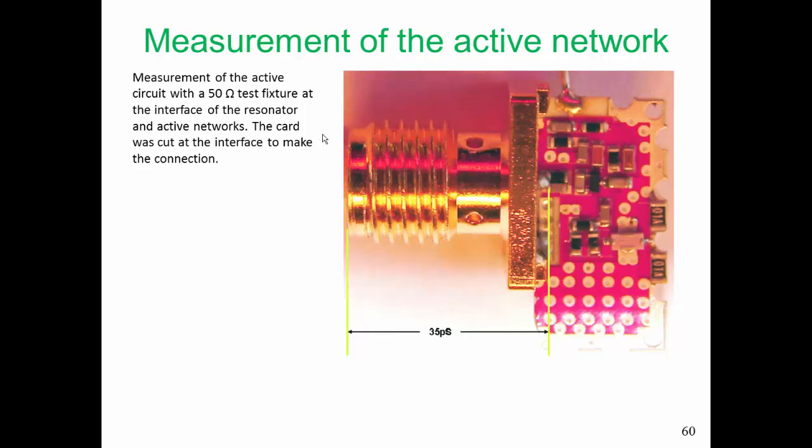And what is shown here is an SMA connector. So these are very small connectors. This is about 4 millimeters across here. So this is certainly blown up. And on the right hand side here we have our connection. There's a pin coming out from the connector. And this large block here is our flange. There are going to be field lines that terminate on the flange. So we are changing our active network a little bit.